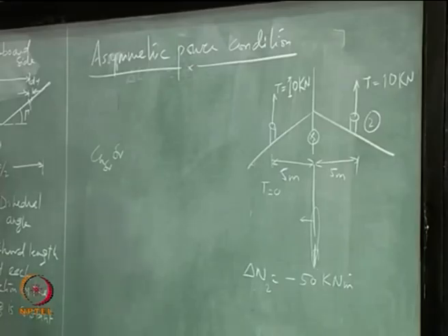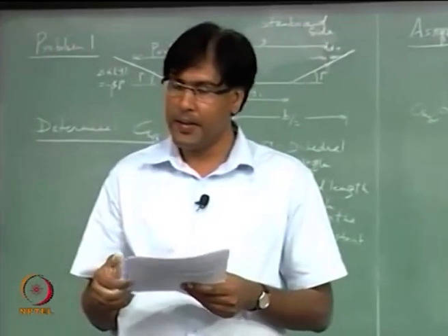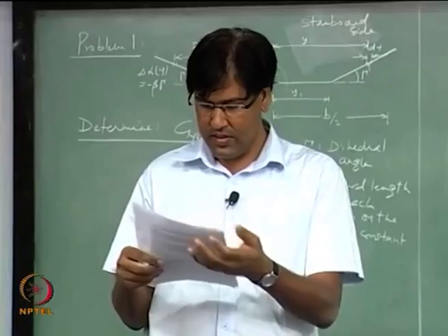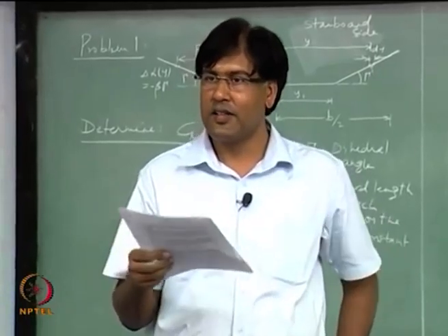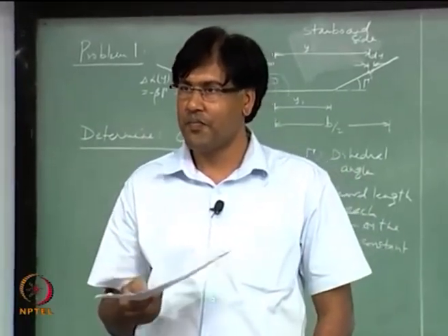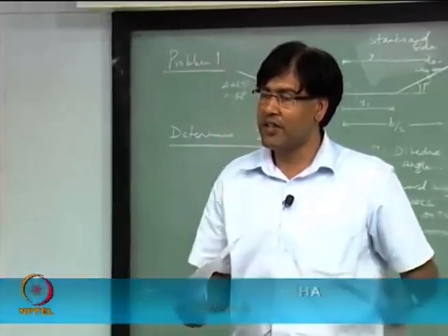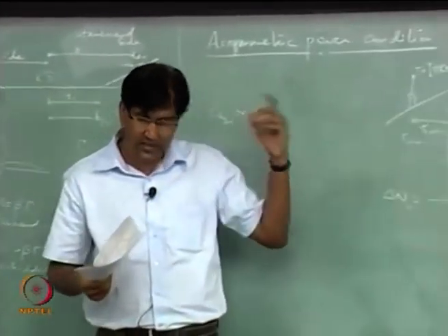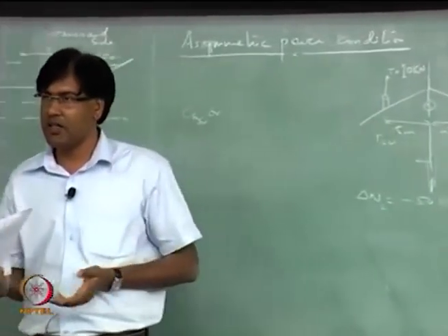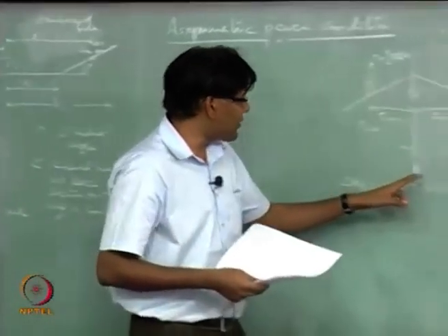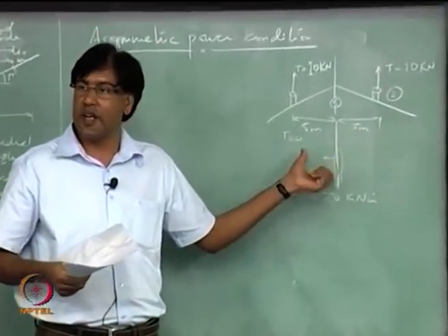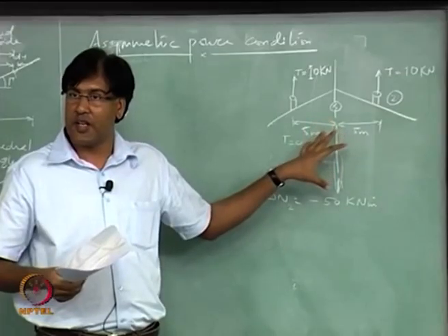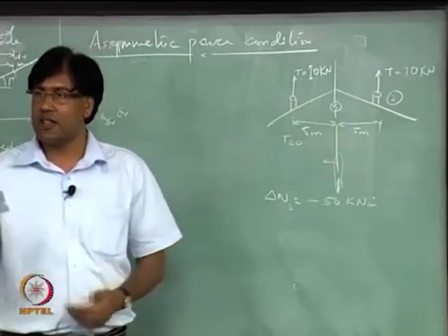And that deflection of rudder is what, negative or positive? All control derivatives are negative, right. So, positive rudder deflection should give you a negative yawing moment, right. So, here I am deflecting rudder to this side and it is giving me a positive yawing moment. So, this deflection on this side is negative.